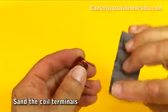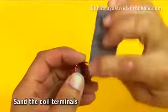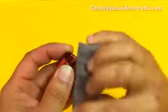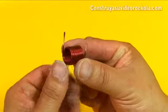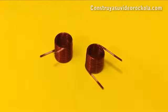Now, as the coil will be soldered to the PCB, we must remove the dielectric varnish from its terminals, so that later the solder will stick. For this we use coarse grit sandpaper, in this case, grain 80. We must be careful not to mistreat the coil, not to deform it, and also not to scrape the spiral's enamel. This work is done with great care. We make 2 equal coils.